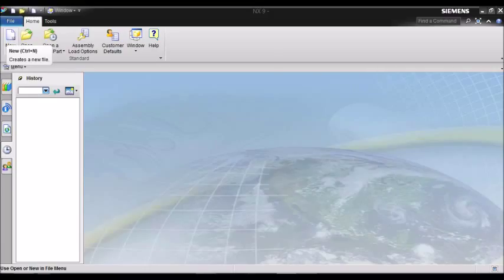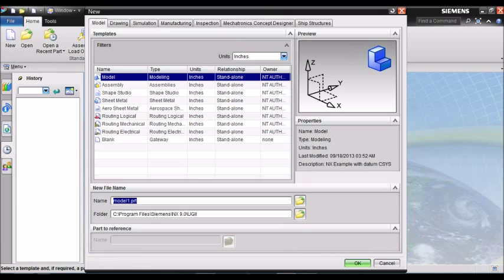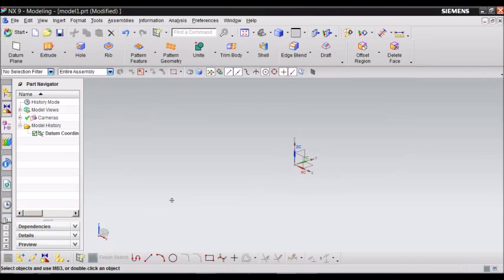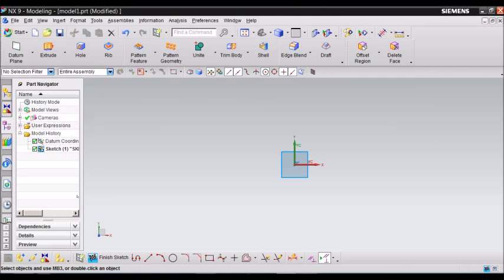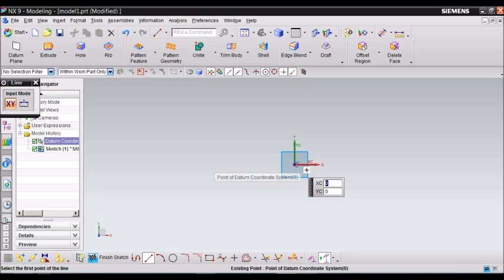Remember, always when we start a new sketch or a new model, you go to New, then we go to Insert a Sketch. We're going to continue working with the XY axis, and we're going to create the triangle there is in chapter 6. To do this, we're going to create a triangle and remember always to start from the origin.